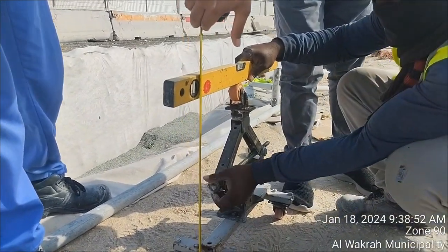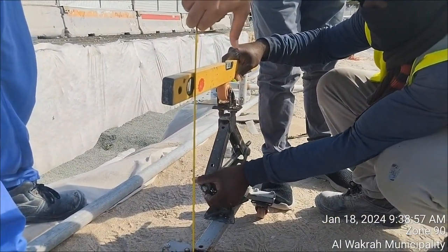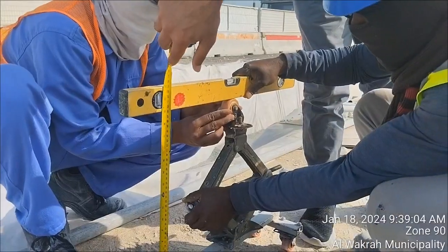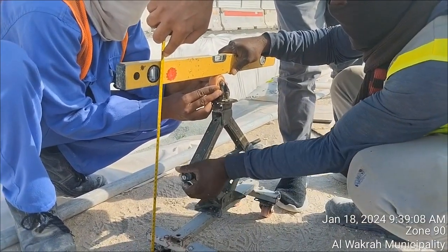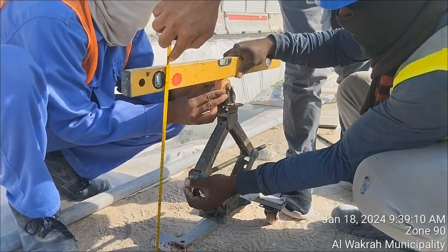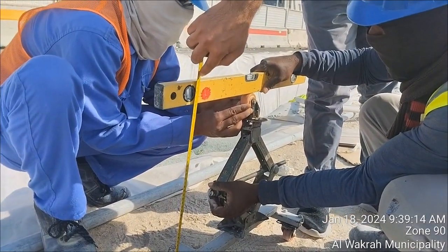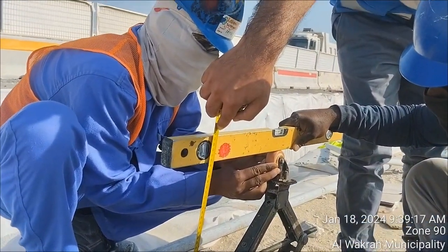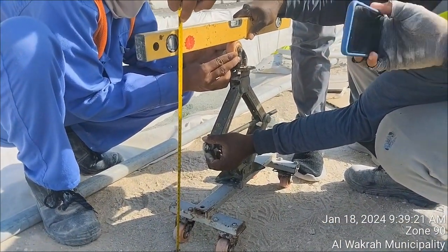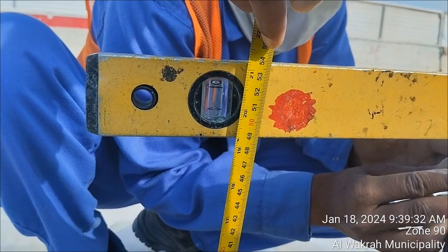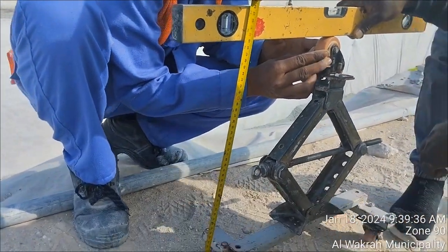This is the lower part of the wheel. Now here you can see we are leveling this. If the level is okay and the height is according to the diameter of the pipe, then we properly fix it. As you can see here, we are fixing the downside now. If it's okay, then we proceed to lower it into the manhole to conduct the Mandrel test. You can see it later in the video.